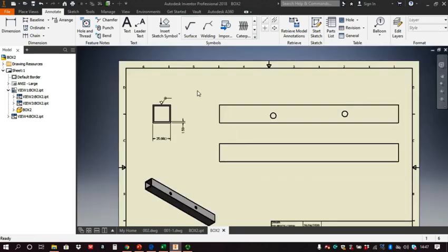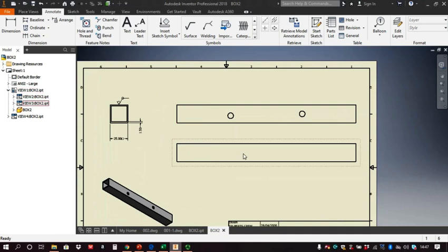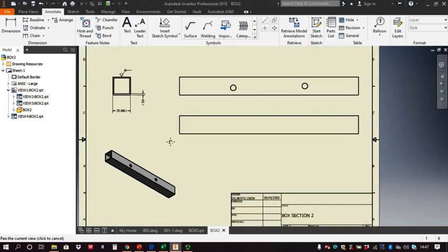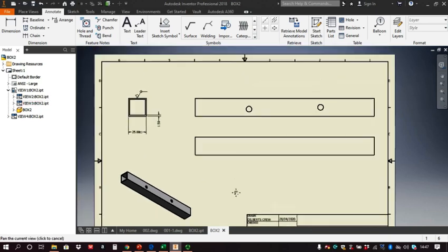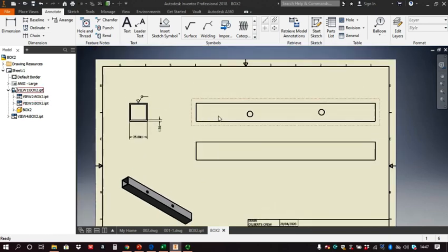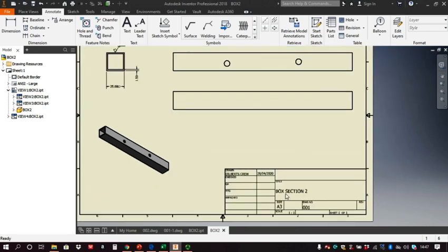Why not drop it on that end? It doesn't matter really where I put it, could I put it over here, it doesn't matter. Okay, so this is the part name. So title box section 2. I don't need to now put a part name because I've only got one piece on this drawing. If I had two, I would have to put a title and the number corresponding to them with them. But because I've got it here, box section 2, 001, I could change drawing number to part number. That would be easy enough.